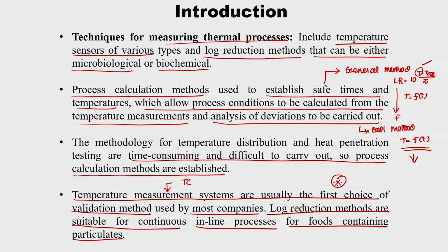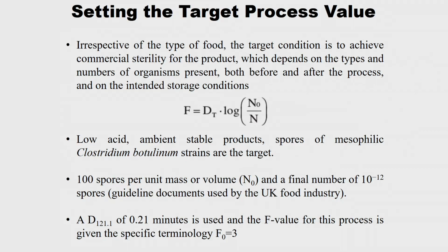So when you have a pure liquid or liquid with particulate materials, it is convection. When you insert the thermocouple, it may hinder the heat rate or heat transfer coefficient. Because of that reason we don't use thermocouples or direct temperature measurements in the inline process. So there my log reduction method would be favorable.